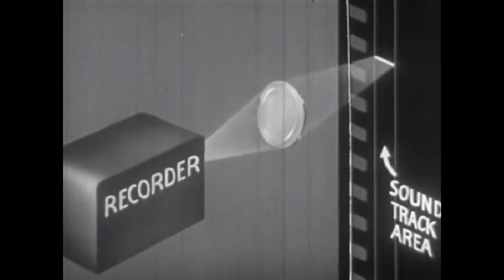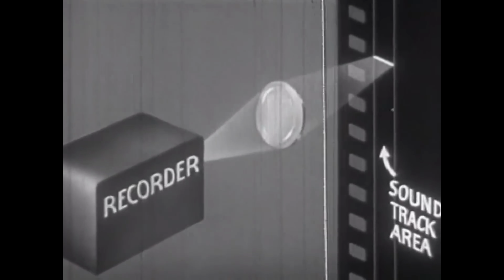The part of the film on which the line of light falls to make the photographic sound record is called the sound track. When the line of light is so placed as normally to extend part way across the sound track, and the sound-controlled variations cause the position of one end of the line to move transversely of the track, a record known as a unilateral variable area soundtrack is produced.